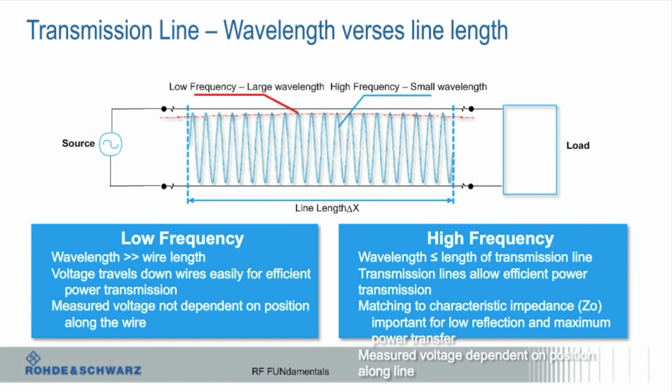So you just make the assumption that the phase stays the same over the transmission line, which was a good assumption. But as you've gone up in frequency, the wavelengths get shorter and closer to the dimensions of the device. And that's where you get into more RF microwave type effects. You have to worry about the characteristic impedance and things like that.